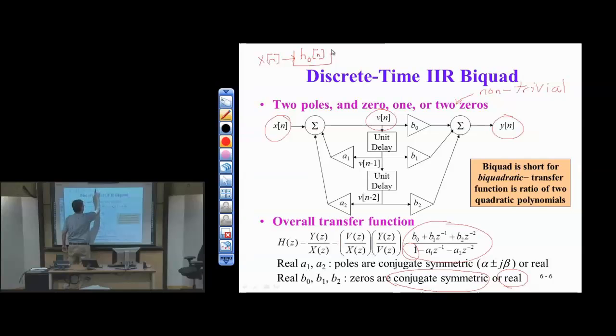V goes through another LTI system to give me y. Now the system that goes from v to y is something very familiar to us from previous lectures, and this is just a finite impulse response filter. So if we look down from v of n, the term here after the delay block is v of n minus 1. And we have v of n minus 2. Excuse me, to go to y of n,